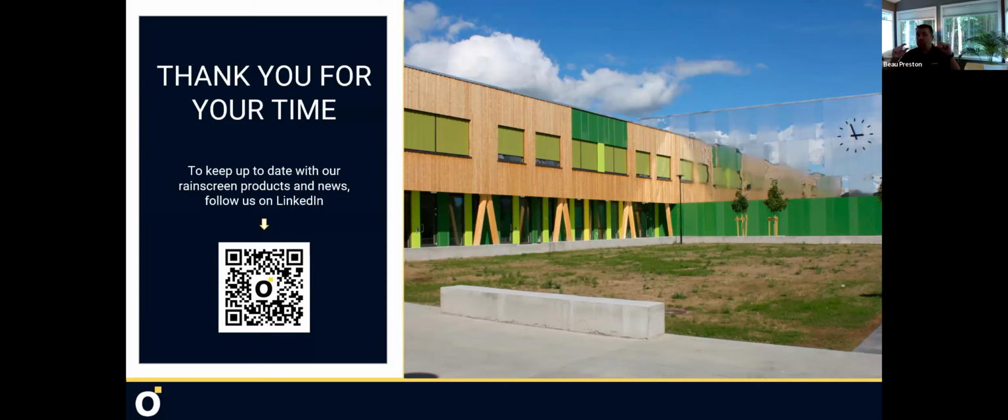They take a stone dust and resin powder mixture and impregnate that whole bit, and cure a panel that's 6 millimeters. Then they either put the aggregate on the face or glass, if they do that of the Steny nature, or they do an image. They do a base coat, and then they'll either print the image or put their color and sheen and all that on it. It is all reinforced.